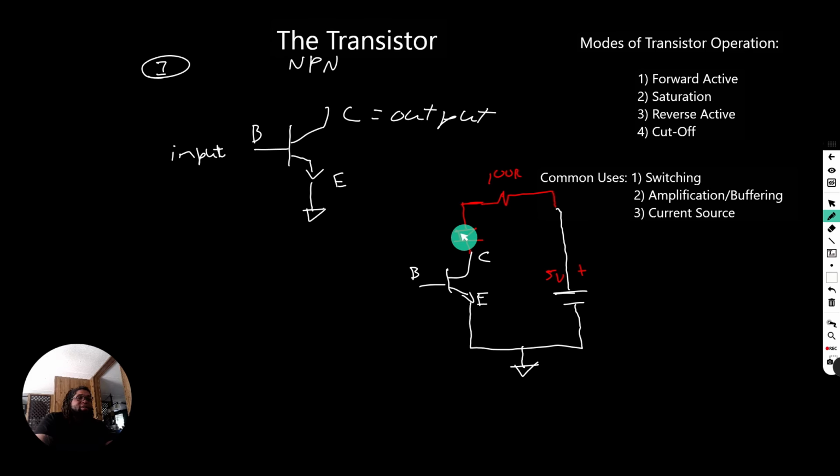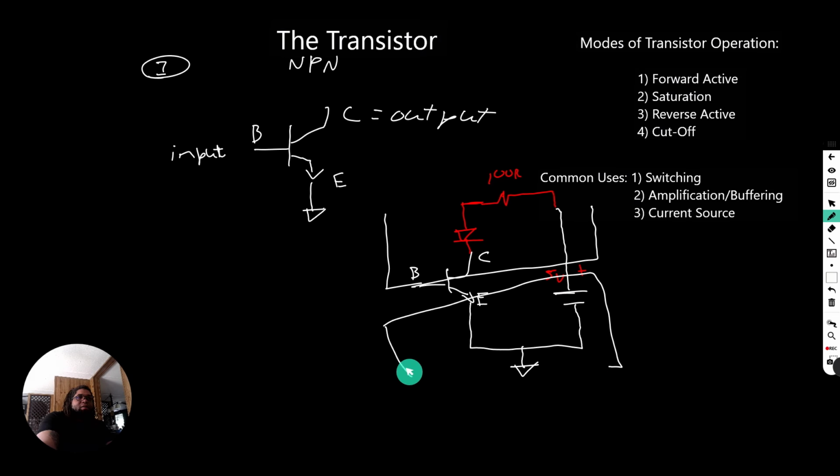but there's not a completed circuit, because this end of the circuit does not see what's going on at this end, because the transistor isn't conducting. Okay, this is what we would say: the transistor is at cutoff, right? It's not operating.